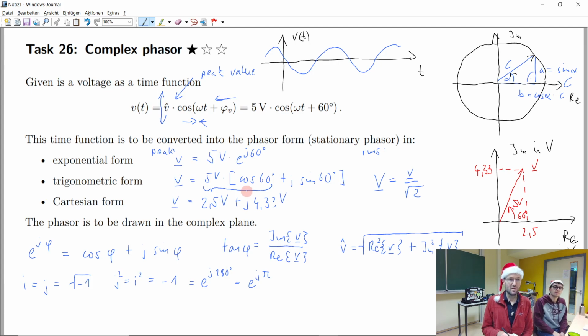If you also care about energy and power, and if you would do measurements in a real circuit, right, with the multimeter that I've shown you, unfortunately I don't have it with me today, but on top of the multimeter you can check some of the recordings of the old exercises. There's something that says true RMS, so what the multimeter measures is the RMS value of some current or voltage. And so, of course, if you want to compare a measurement with your calculation, you need to compare with the RMS value and the RMS phasor.